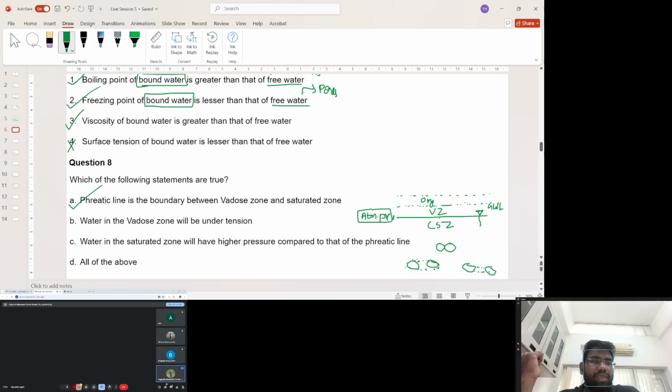So that is why, since you are exposed to effective stress problems now, the pore pressure above the groundwater level is negative. That is the sign convention we use for compression and tension. Tension we consider negative and compression positive as far as soil mechanics is concerned, which is slightly different to what you are usually exposed to in strength of materials and solid mechanics, right? So this statement is also right.